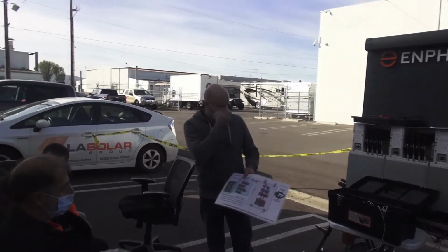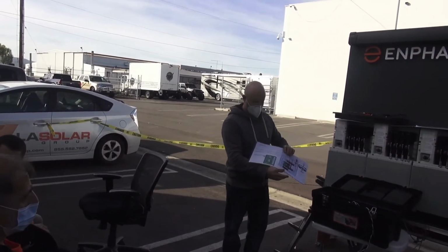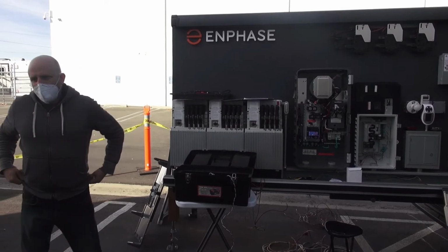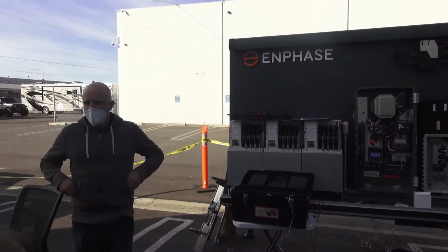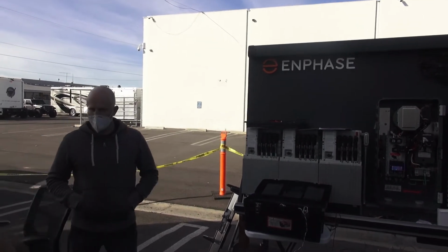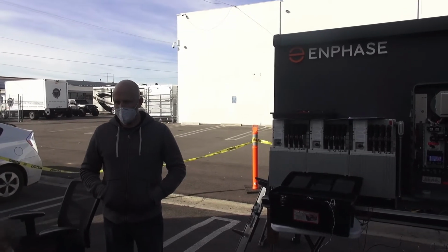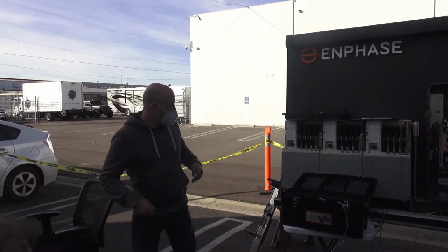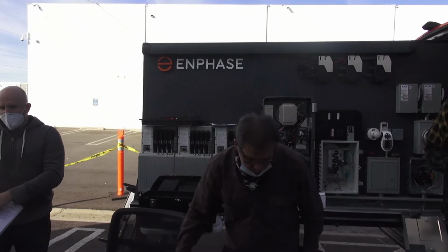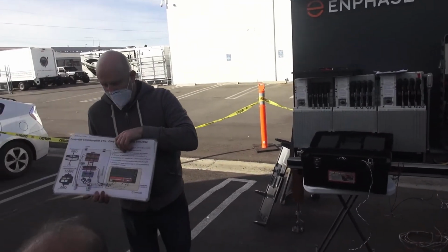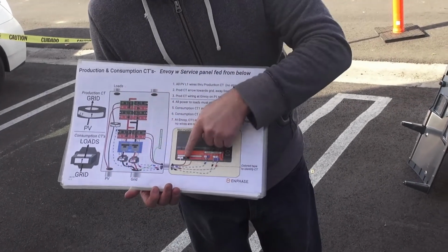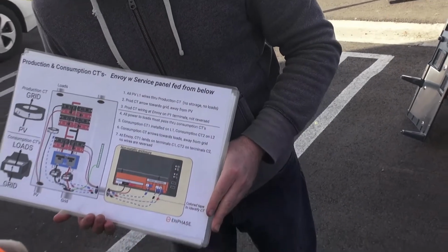Question. A lot of times we get massive jobs, massive amounts of solar, so we cannot use the Enphase combiner box because it maxes out at 80 amps. Sometimes we have up to 200 amps. So we have to do our own sub panel and a separate box just for the Enphase Envoy. The CTs that come with it for production, 200 amp rated, correct? Looks like this, right? Yep. So in that case, you'll install your own separate box. The CT has about a 6 foot cord. That was my question, how long are the cords?